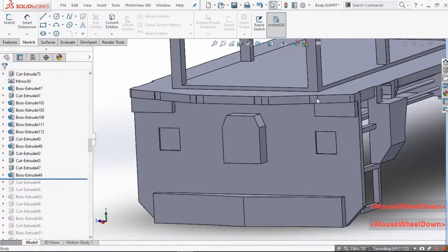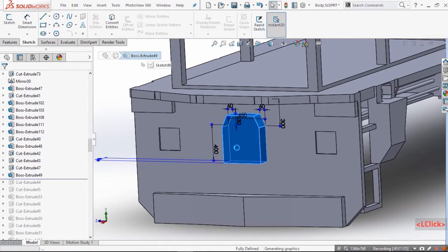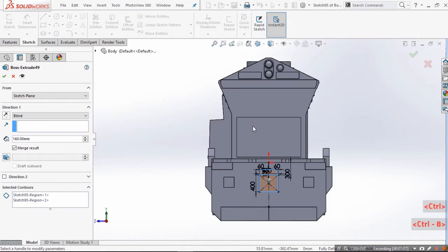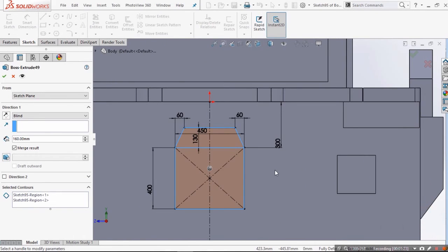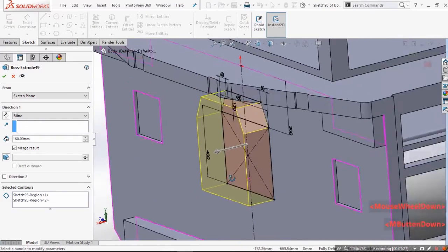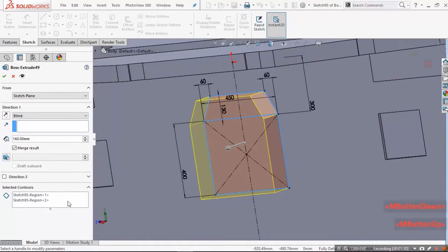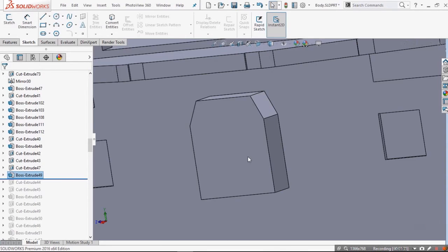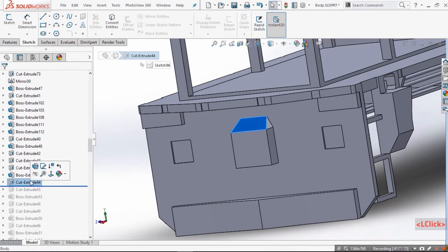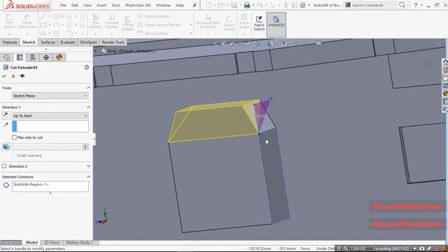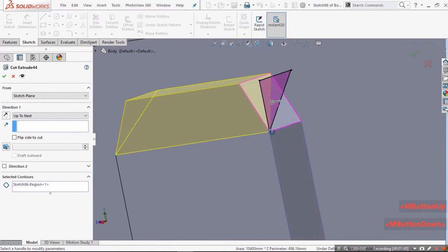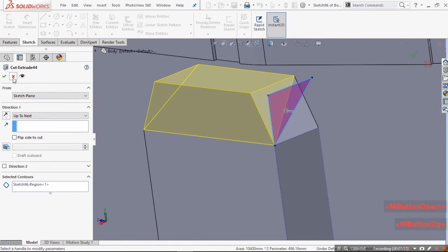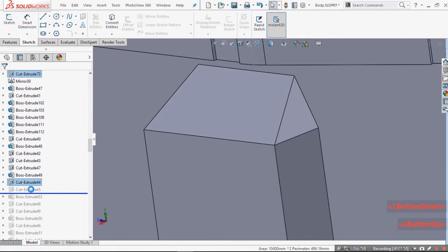Now this is what I have made for the coupler of the locomotive. Again, this is a simple boss extrude of an assumed sketch with visually similar dimensions. Instead of wasting time trimming out the unwanted entities, we just select all the closed boundaries in the contour section to save time. This is just a triangle made on the side surface, and I have used extrude cut here by giving the up to next constraint. Don't use through all here.